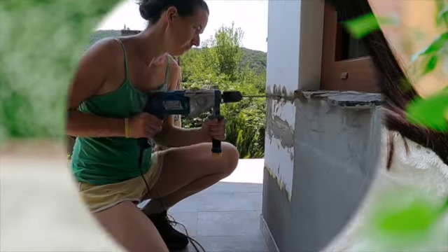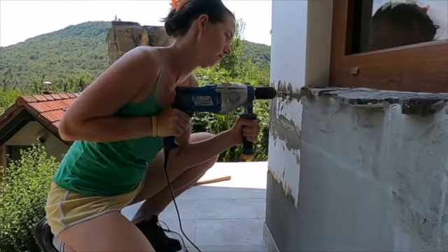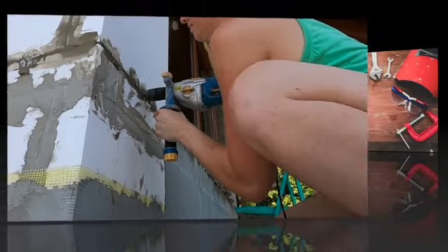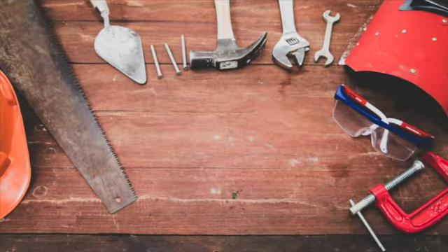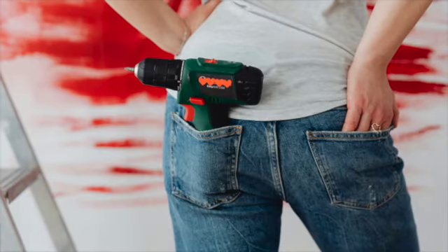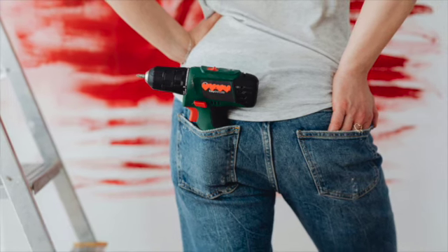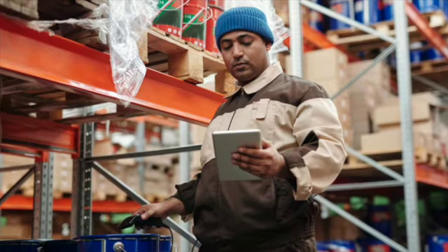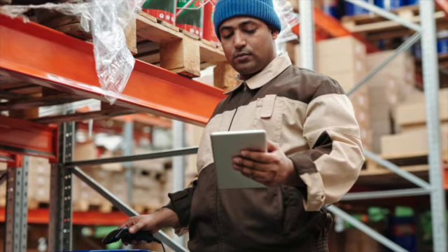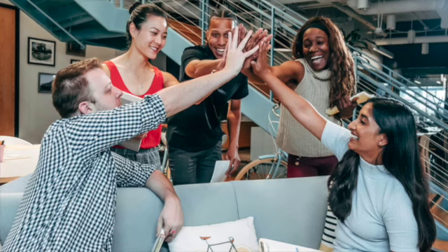For instance, if operating a power drill, make sure you use the correct drill bit for the material and avoid overloading the tool to prevent malfunctions. Improper storage can also lead to accidents. For example, avoid leaving power tools on scaffolding or ladders where they can fall and injure someone below. Store heavy equipment in stable, designated areas away from pedestrian pathways. Safe equipment handling protects not only you but also your colleagues.